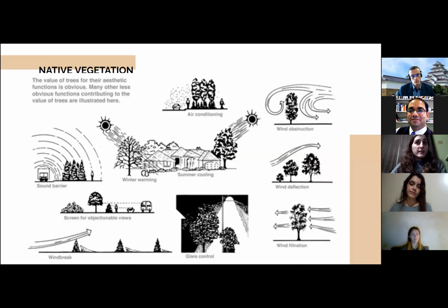To prevent the solar incidence on the most vulnerable facades, native vegetation is used as a protection. The predominant presence of trees and shrubs of different and varied dimensions will lower the temperature of the place, generating a microclimate. So the vegetation is used as a passive cooling strategy since it allows to manipulate the winds, taking advantage of the volumetric shape of the context. And this integration of native vegetation in the project helps to deal with the need for humid air to control the evaporation.